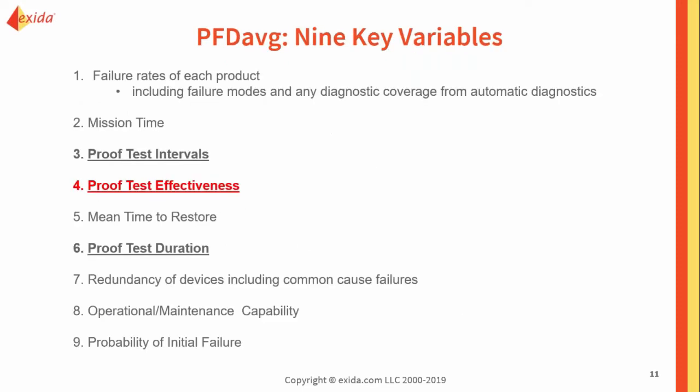But why does this all matter? Well, yes, doing a proof test to check the functionality of the device is good, but it's really so much more than that. Remember, the real objective is to detect those failures not detected by automatic diagnostics. And that becomes a big deal when it comes to your SIL calculations, such as your probability of failure or your PFD average. Those SIL calculations want to look at that risk reduction possible.